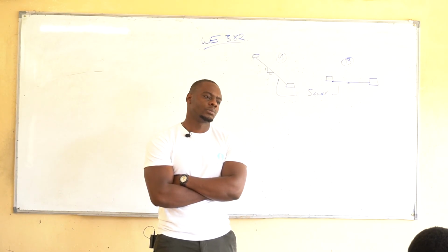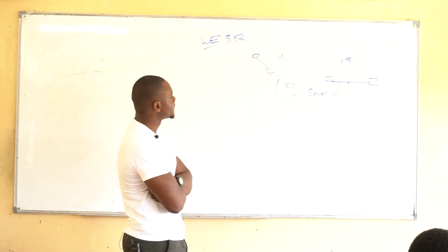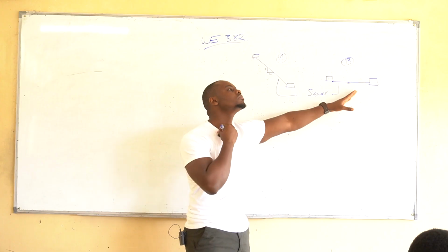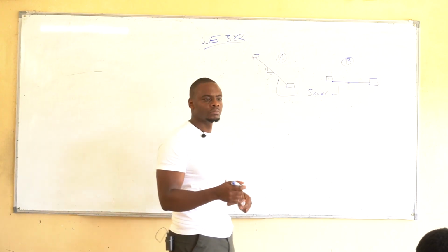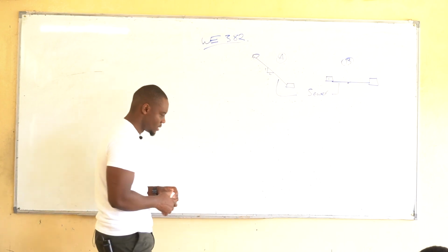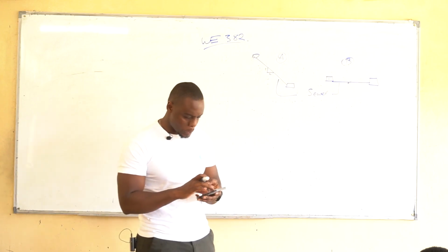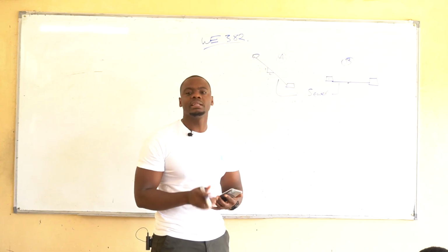If we lay a pipe like this, like the B, which pipe, A or B? We are likely to experience clogging because the slope is not enough for the pipes to clean themselves. Then also the pipes are likely to burst. Did we get that?